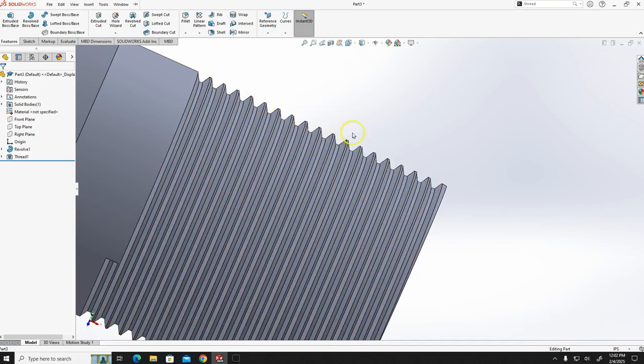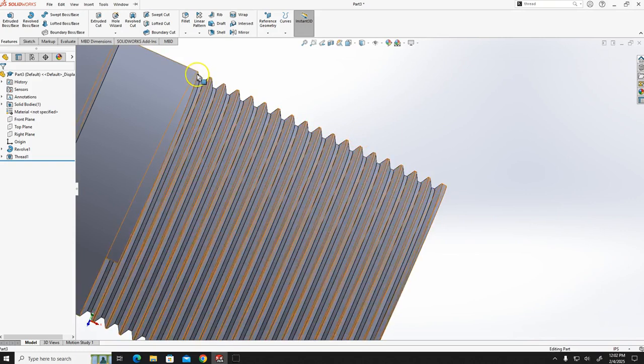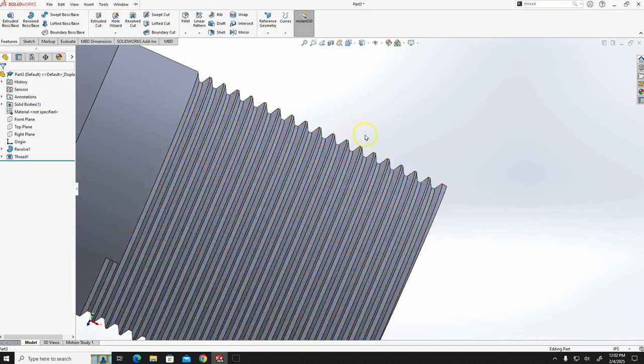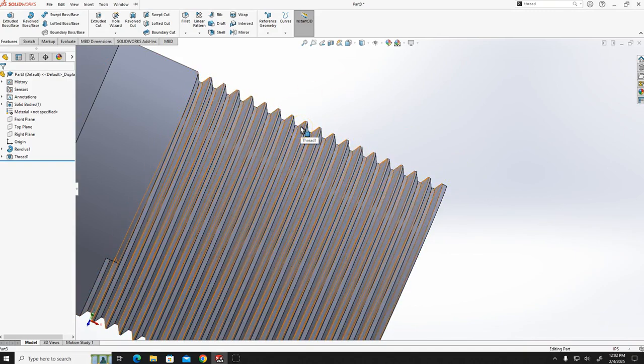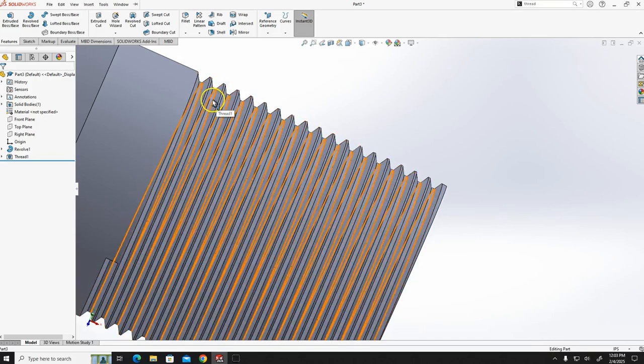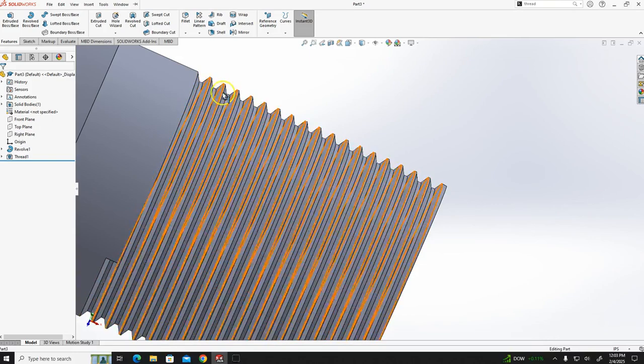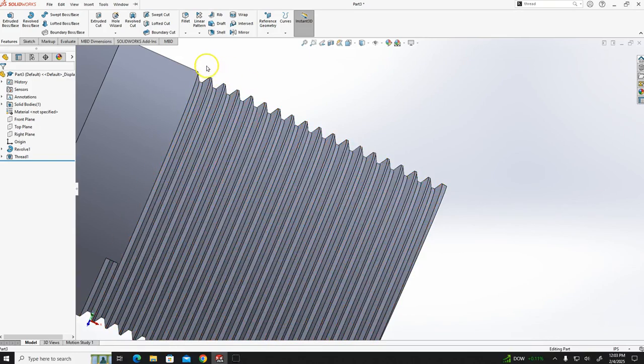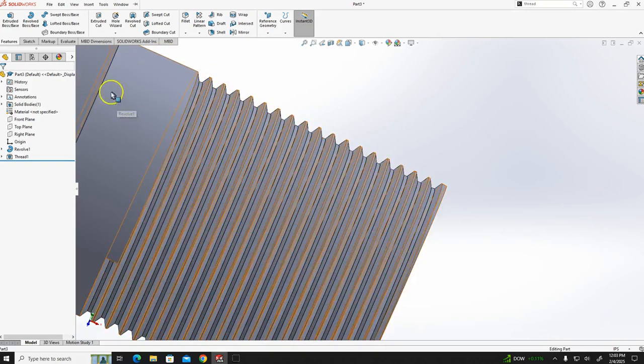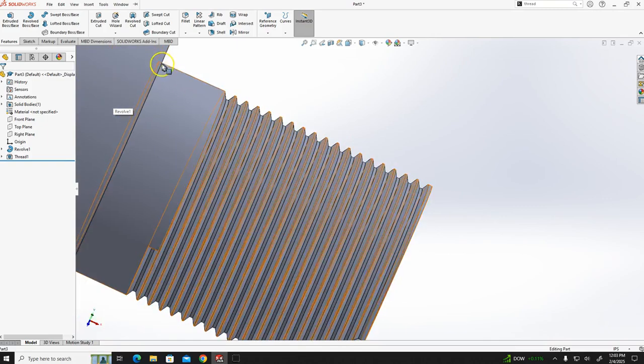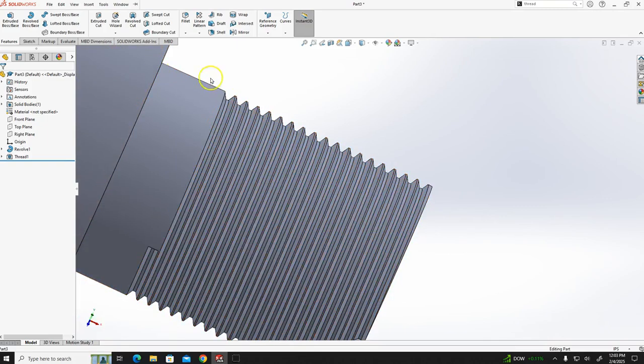So for 1 inch we have specified 12 threads. So that's why, this total length is 1.5 inch, we will have 12 into 1.5, so that will give you 18 threads onto the total length, that is the 1.5. Okay, so similarly if you change that length to say 2 inch, you will have a total of 24 threads onto this length.